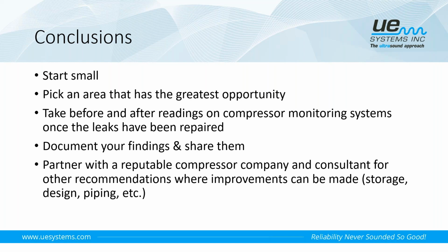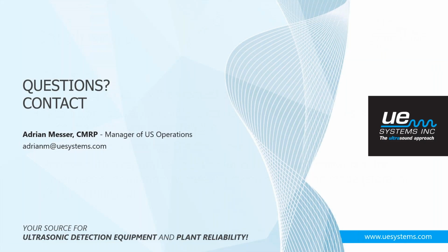But I'm telling you, if you start with a leak detection survey and then you repair those leaks, you'll see immediate improvements in your efficiency, and a lot of times you can totally bypass having to get in additional compressors to keep up with the demand. So with that, we'll open it up for questions if we have time.